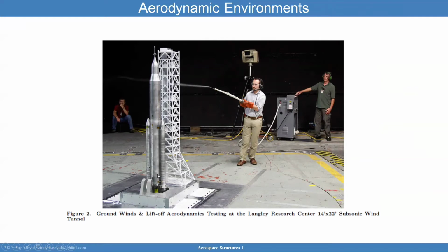And so you can use scale up factors to come up with the loads it's going to experience when you go full scale. But if you create a CFD model of this vehicle with a wind tunnel test, you can anchor that model to this scale model and demonstrate that that model is adequate, and then go to a CFD model of a larger scale to try to see if everything is making sense.